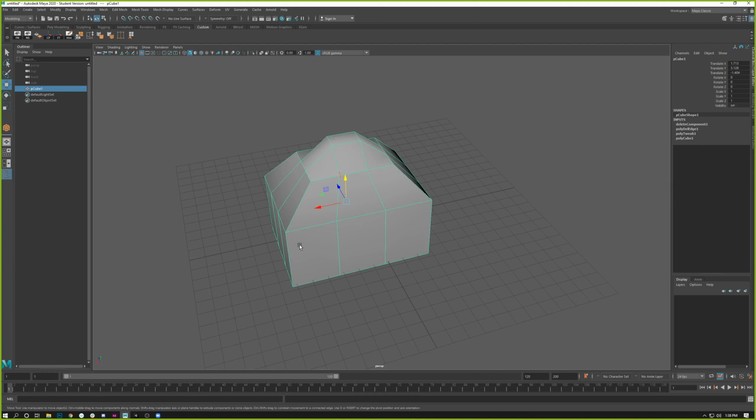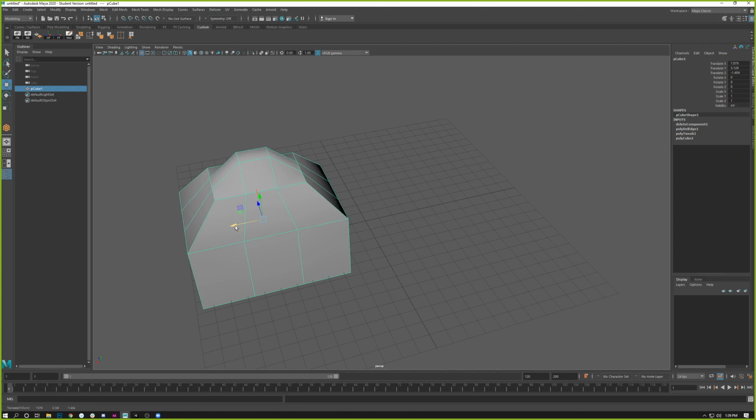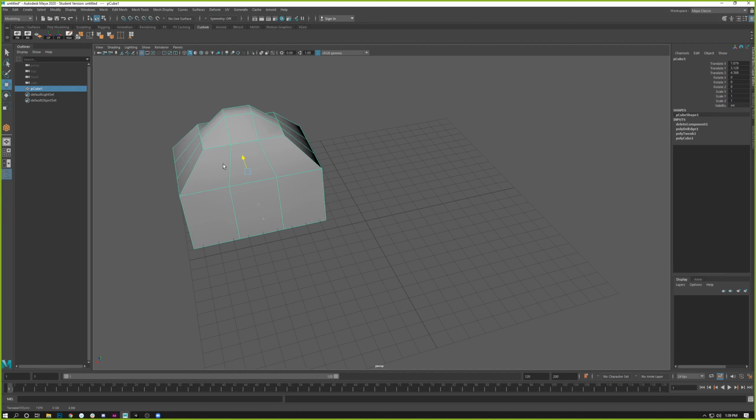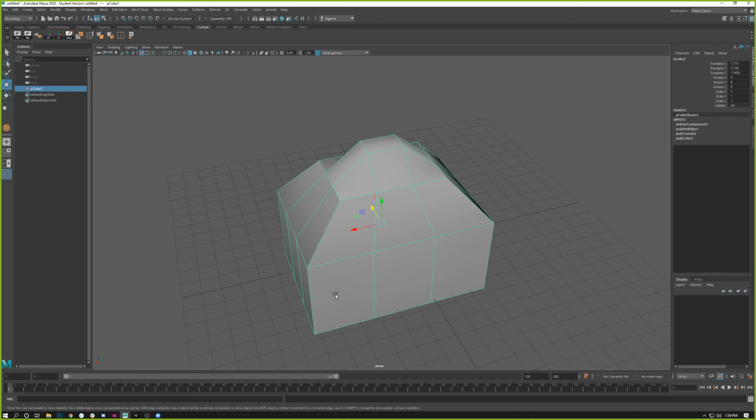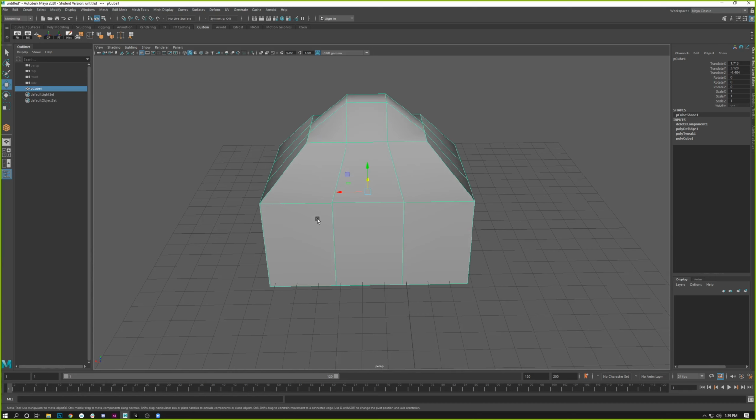So we deleted faces. We talked about deleting edges. How do we get edges back? Again, there are several ways of doing this. You can do it at the inputs when you first create an object, but that's only good when you first create the object. After that, the inputs are a no-go. You can't go back to the inputs. This is one of Maya's weaker points, I would say. If you mess with it, it's probably going to break. So you don't generally use inputs and change the order of polygon count after you start manipulating the object.